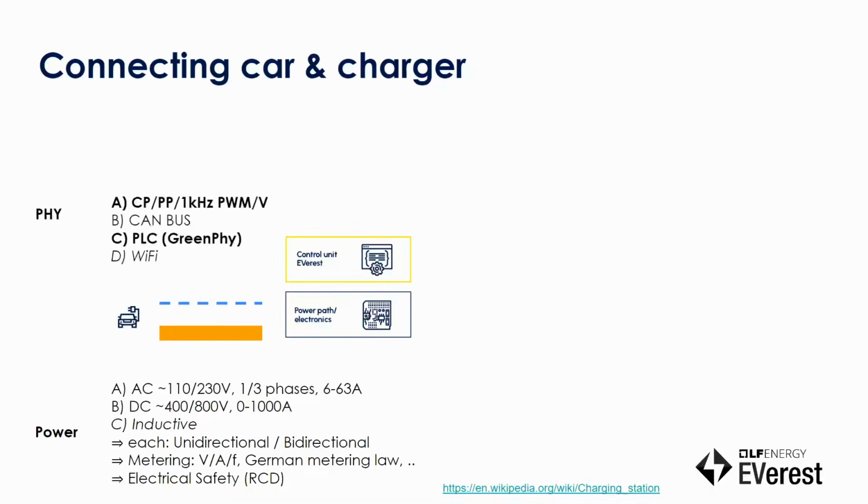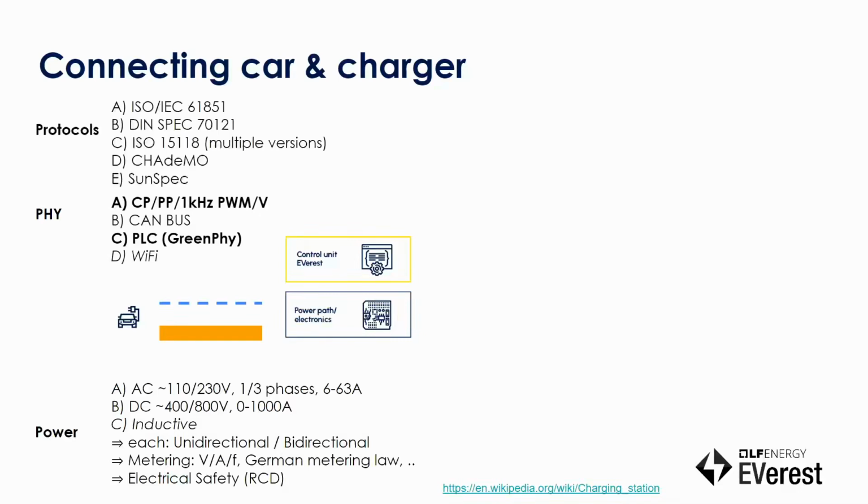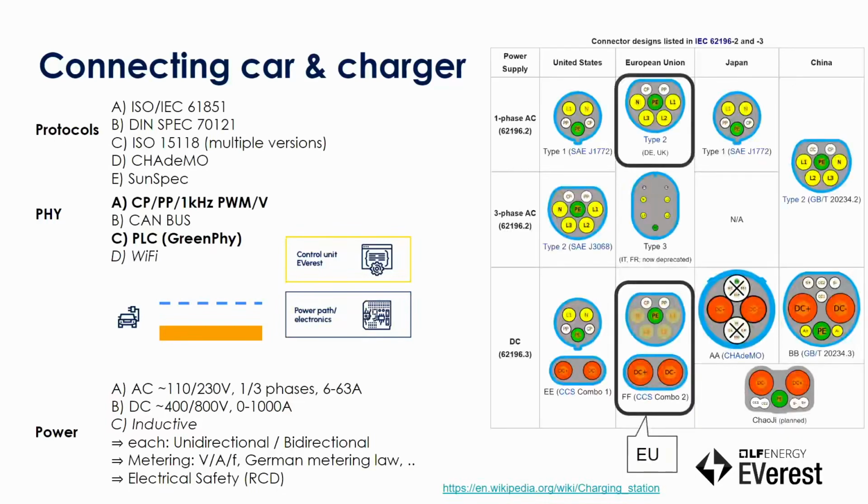On top of that, you also have a data link. There's a physical layer, how you can transfer that information between car and charger. There's a really dumb version where you just have a PWM signal, which is often used, but there's also way more smart stuff where you exchange kind of XML messages in a really, really weird format. And this is just an extract of the different protocols you have. And this is just one link.